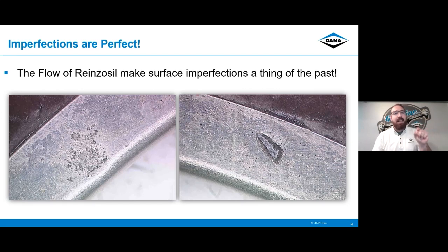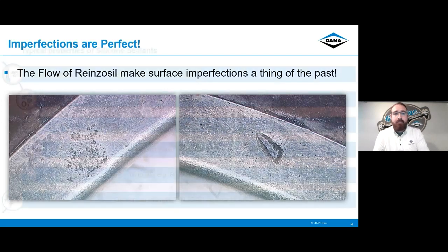So this makes it a little bit of a different situation than, let's say, a metal gasket, right? Where if there are any type of deep valleys like this, or micro abrasions in that surface, silicone is going to do a really good job here for you, as long as you're making sure that it's clean and it's taken care of.